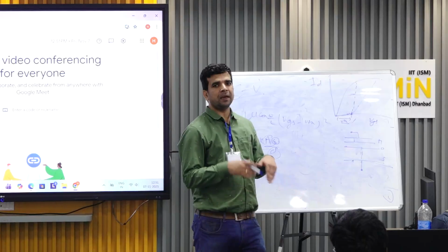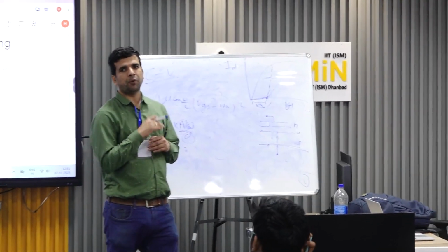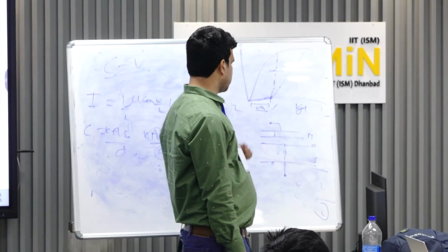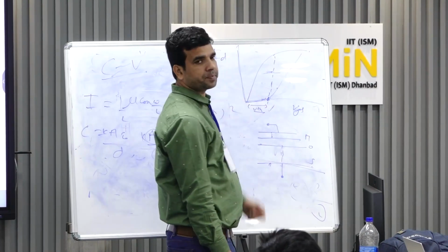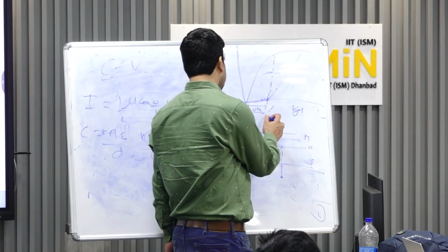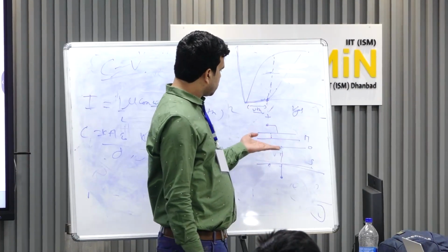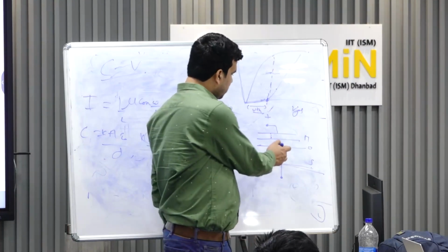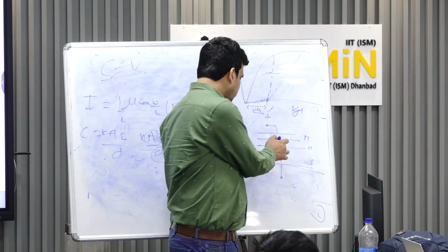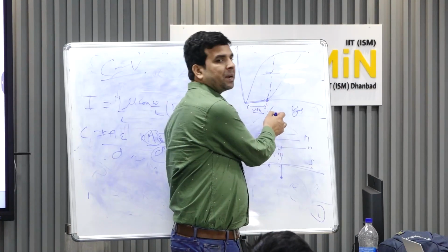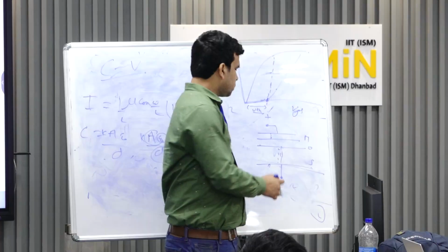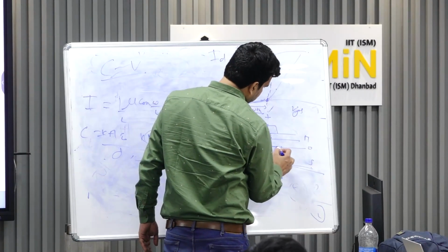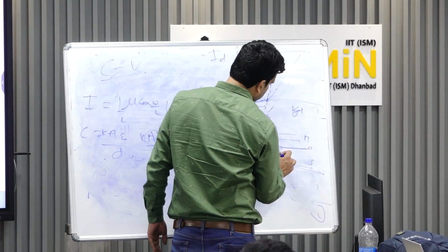But what happens if you apply an increasing positive voltage across? The moment you start applying positive voltage here, this will start repelling whatever holes are here. So the holes will start moving in this direction, because you are applying positive voltage and it repels all the holes. So near this plate, the depletion layer will start generating here.